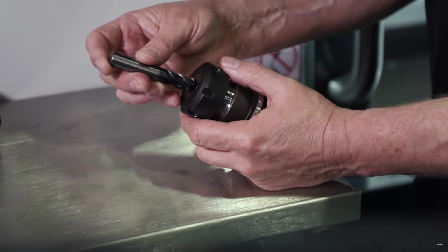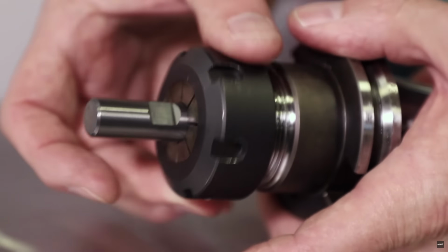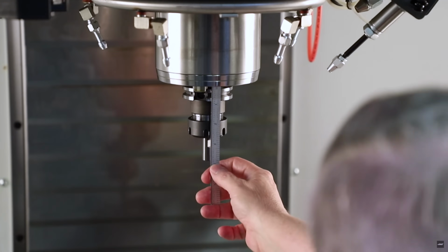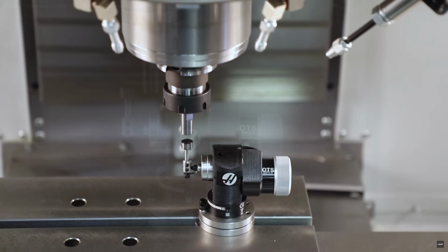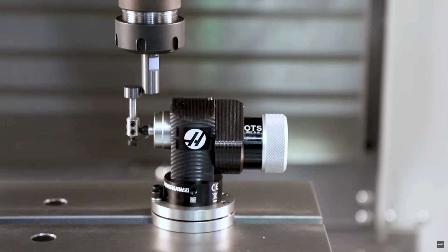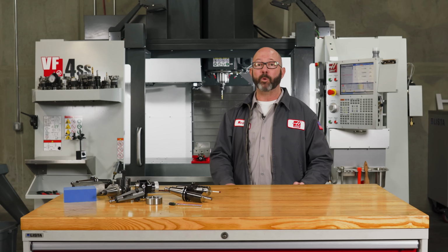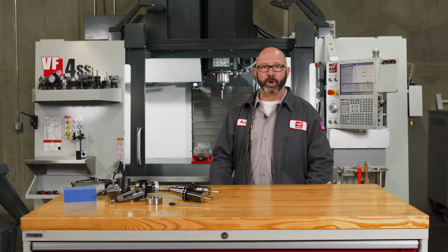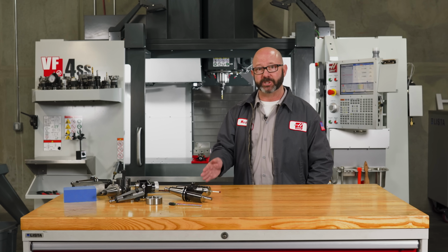It is possible for us to create our own calibration tool by measuring from the spindle face to the tip of a pin in a holder and using this estimated value when we calibrate. This is fine. Our probe won't be calibrated to some industry standard gauge line, but we can still probe and make parts on that machine.